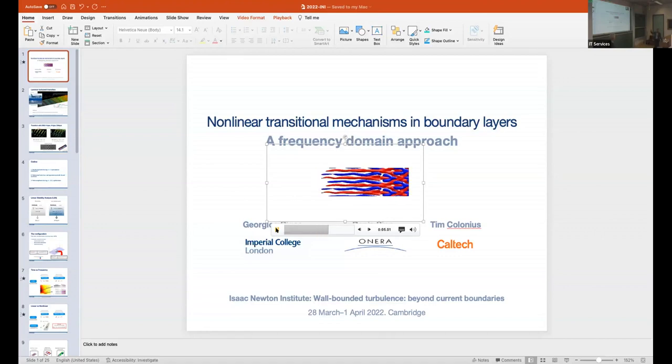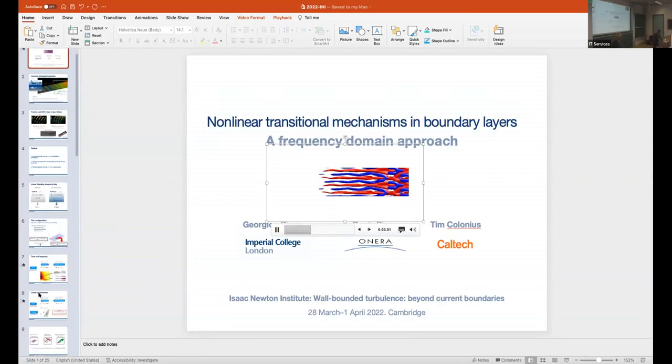So in my case, I call it transition because I've reached the empirical skin friction coefficients. And actually, if we look at the energy of the harmonics, this is where I have the explosion of energy to all the harmonics. So I start having a cascade, and that's why I would call this one transition. So you would actually go right up to the turbulent skin friction. It's just that plateau. I guess I'm confused by why you, or is that just a snapshot actually?